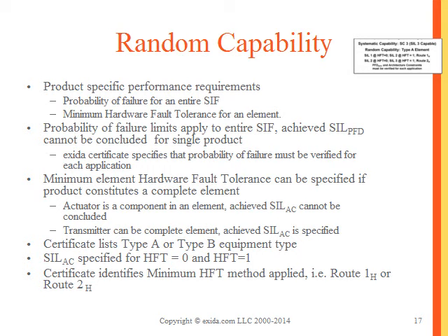We see similar items in IEC 61511, where 61511 requires initially no redundancy for SIL 1, but then when you read clause 11.4.3 of 61511, it says that if the dominant failure mode is not to the safe state or dangerous failures are not detected, you need to increase that minimum hardware fault tolerance requirement by 1.